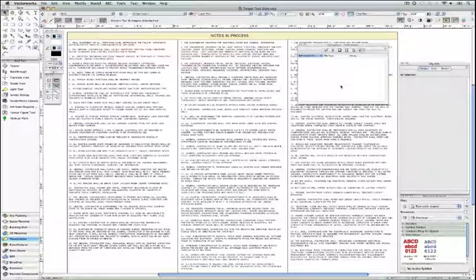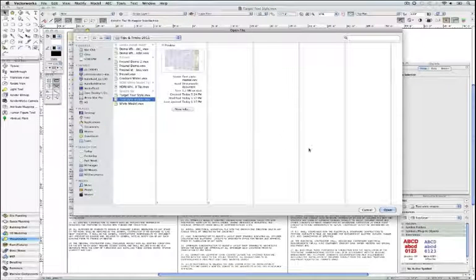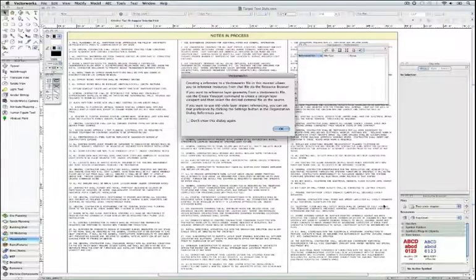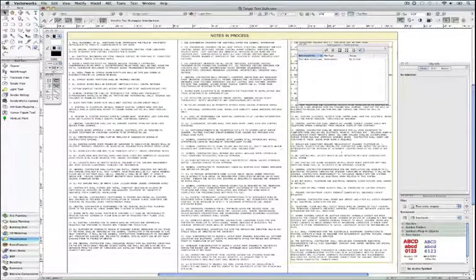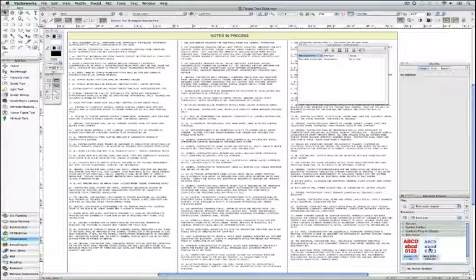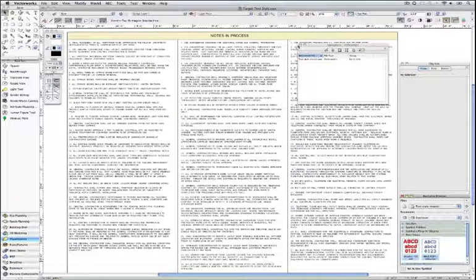Once we're there, we'll open its navigation palette and choose the Reference tab. Right-clicking there, we'll choose New to establish a reference. As you can see, the path will be back to the master file. You can also see the reference file there in the nav palette. Now I'll pick the two text styles from the master file there in the resource browser and choose the option to reference them into the target file.